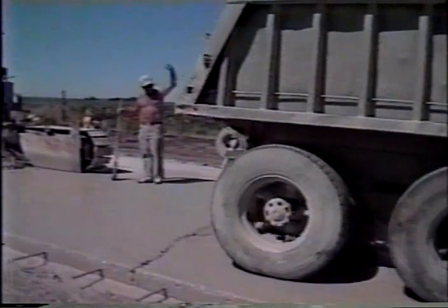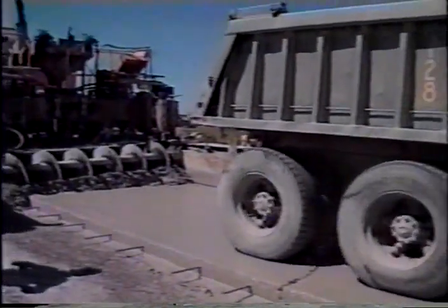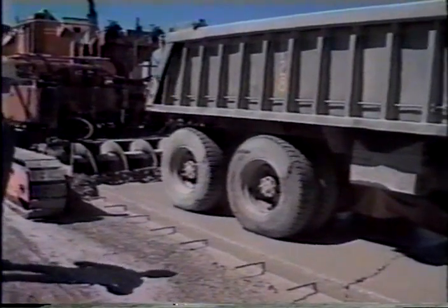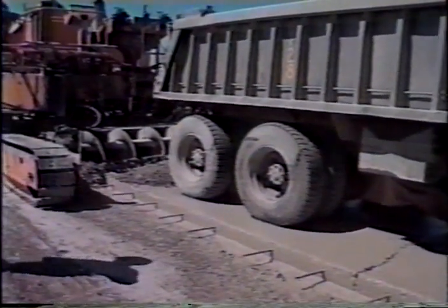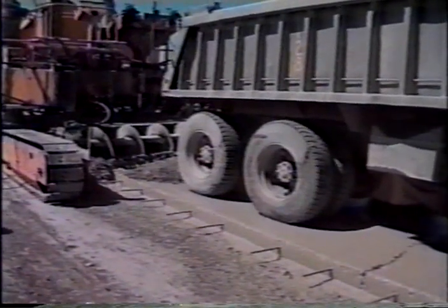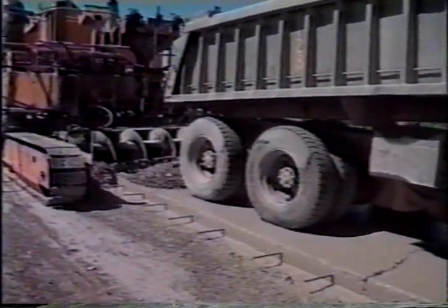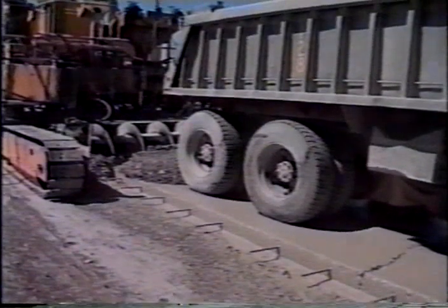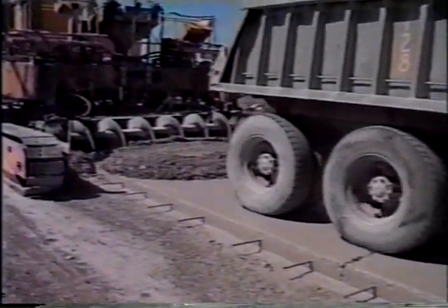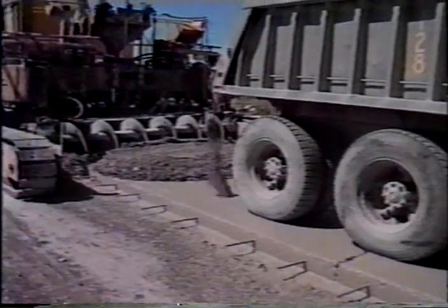The bonding application should stay close to the paving operation to keep the grout from drying. Dried grout is detrimental to bonding. A maximum distance of 8 feet between spraying and paving is recommended. If the grout does dry out, the paving operation must be stopped and the dried grout must be thoroughly removed by either shot blasting or sandblasting.